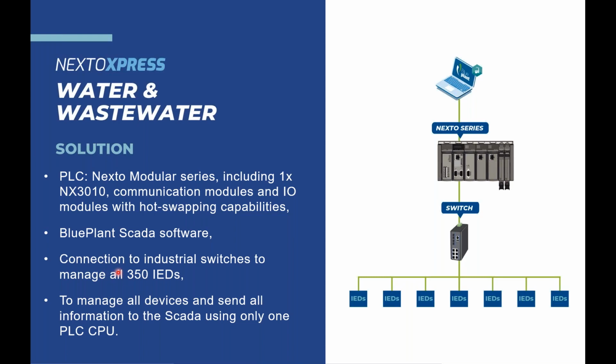Here we have the information of how many IEDs: around 350 intelligent equipments in the field. From the Nexto PLC and from the control center, you can manage all devices and send information from the SCADA to the devices using the Nexto controller. And we have a switch here to connect all the 350